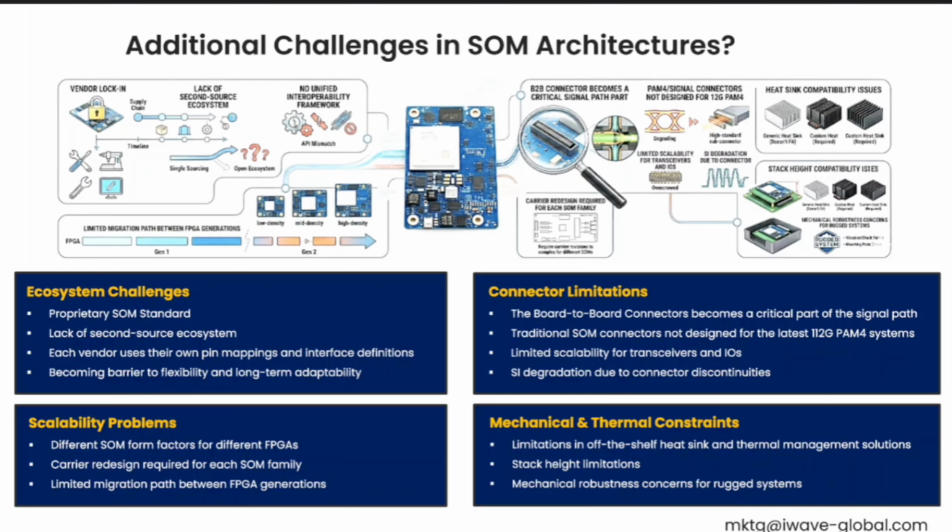Also, if there is a requirement for a compact solution, it is very difficult to adapt the SOM. If there is a limitation on the height with respect to the entire product dimension, since the SOM has a connector with stacked height and it is very difficult to go without a connector, they are forced to completely redesign the board.